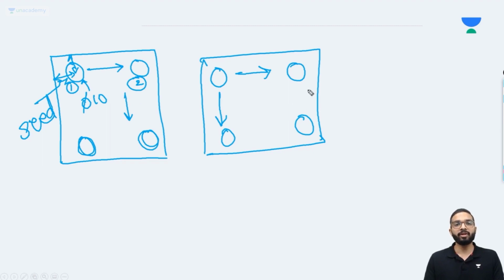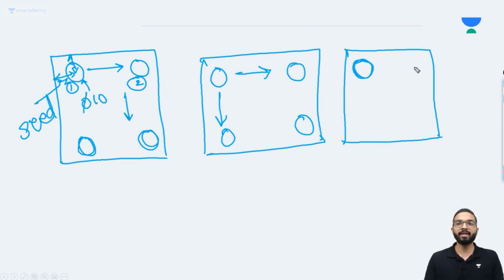Next way of creating this is that we create a sketch. I will show you how. Let's say I have created this first cut over here of our circular hole. Next what I will do is that I will create a sketch specifying the points where I want my holes to be created. Now what we will do, we will go into sketch driven pattern and then give this sketch as my input. I will select this feature as my input feature, or rather in technical terms we will call this our seed. And once I select my sketch, it will generate this hole in all the other directions like this. This is how we can create all these holes in linear pattern.